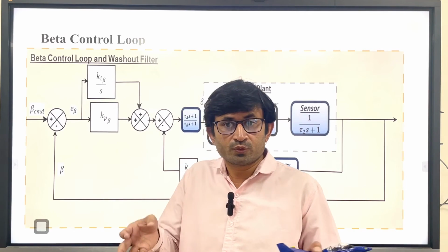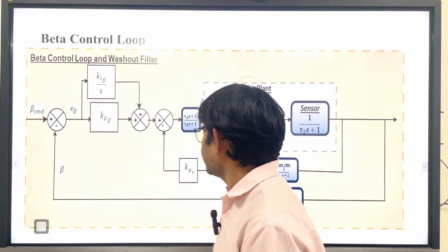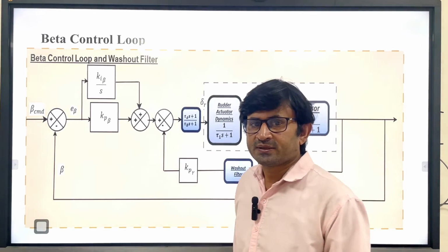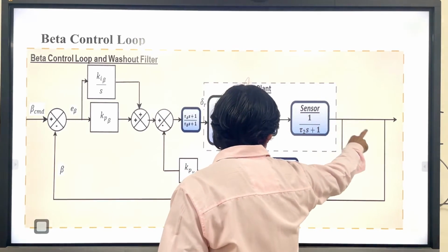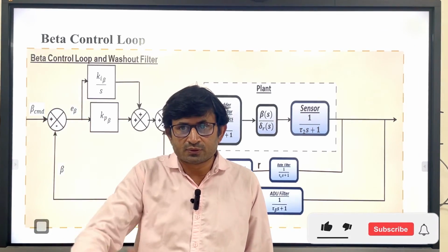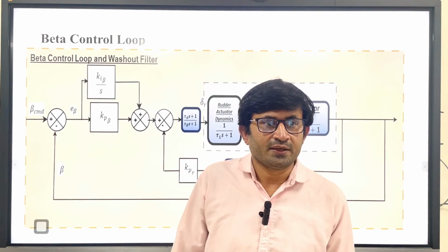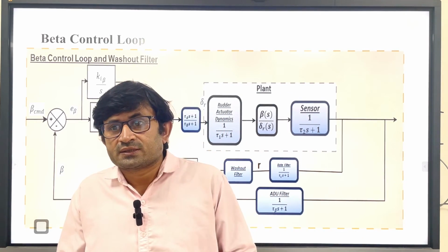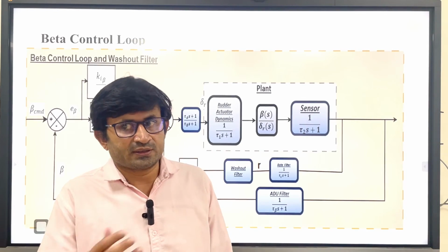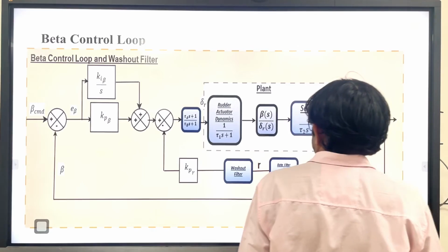So you have to put in the physical limits, position and rate limits as well. Now when I say delay, I am taking feedback from the sensor to the controller, and it takes time to reach the control block, right? So that is a kind of delay. The flight controller also takes some time to perform the computation, which is another delay. So you can consider an 80 millisecond delay.